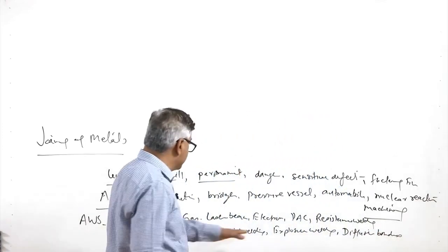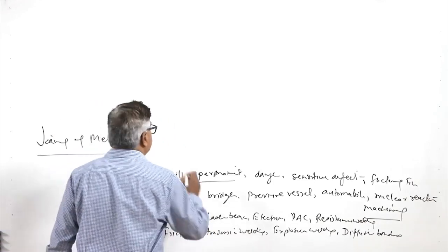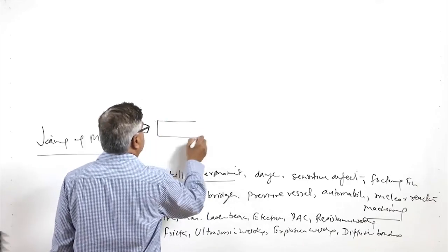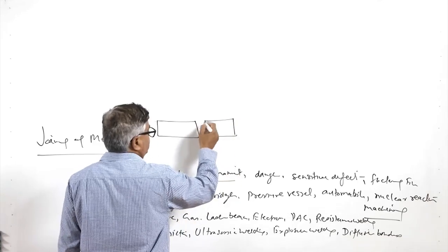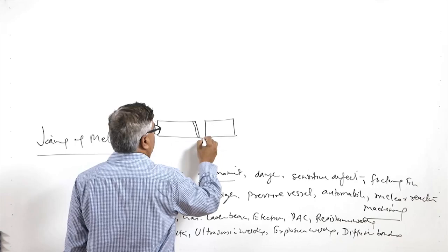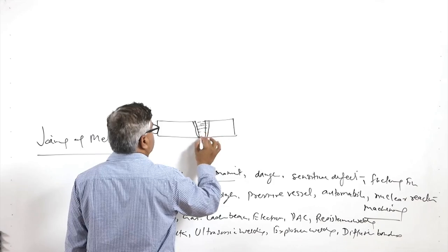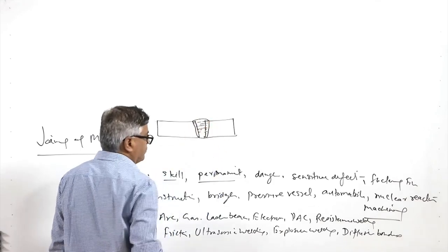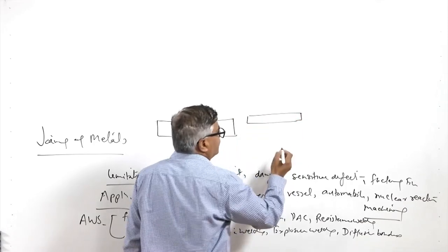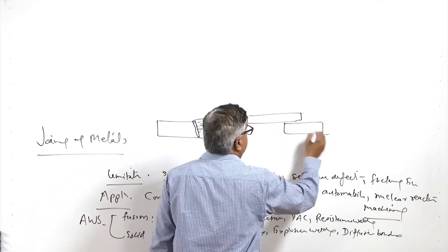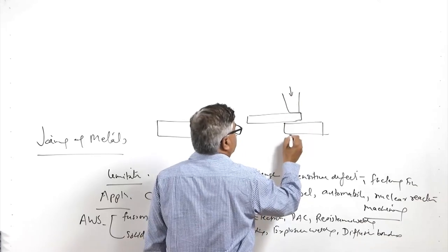Although the approaches are different, in the fusion welding processes, the faying surfaces brought to the joint are melted, so that the metallic continuity is realized after solidification. Like here, spot welding also has been placed, wherein the overlapping plates are subjected to the application of current flow through the copper electrodes from both sides.